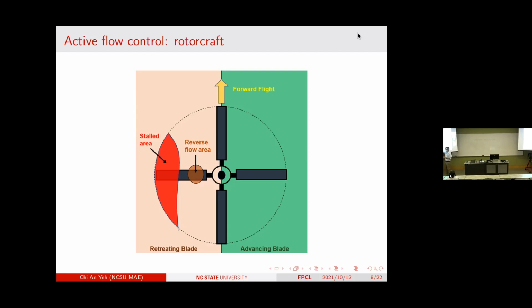One way to do it is to increase the angle of attack down here, so that you somewhat balance out the lower relative velocity on the retreating side, right? That's how they end up balancing out different lift from the advancing phase and the retreating phase.